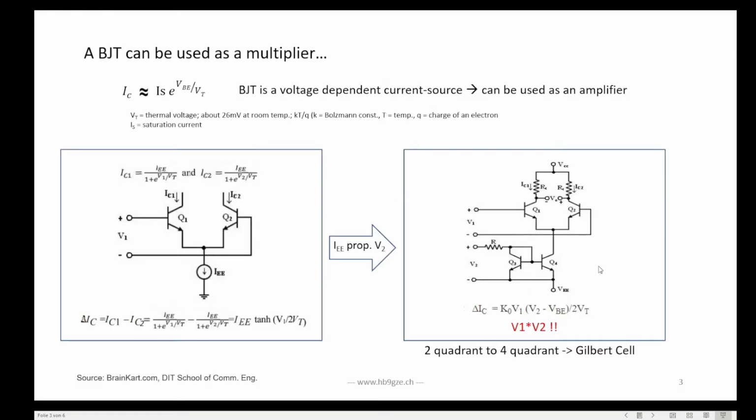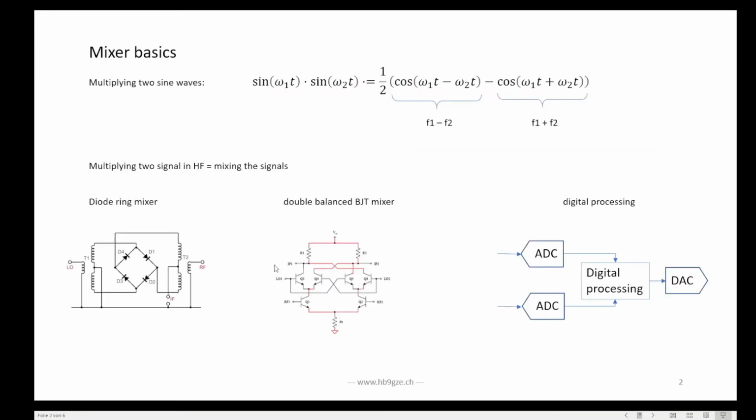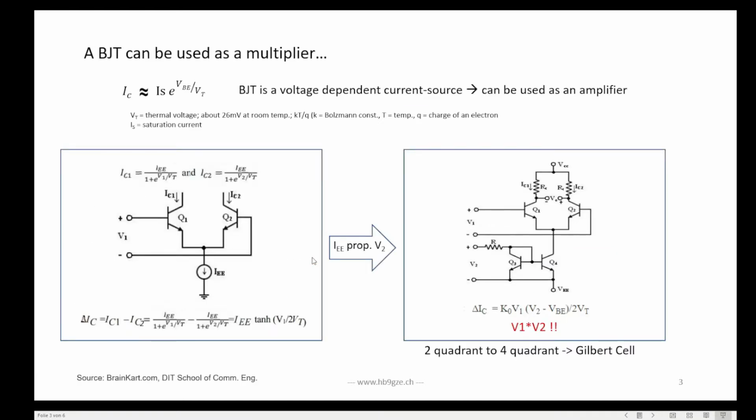So there are these methods. And maybe what's interesting, if we take a closer look at these active mixers, these are the ones that you usually use today, because with these passive mixers you have a pretty high attenuation. You need an amplifier before or after or on both sides of this mixer to have a reasonable signal level to work with. It's easier than with these solid state mixers. They usually have also an amplifier on board.